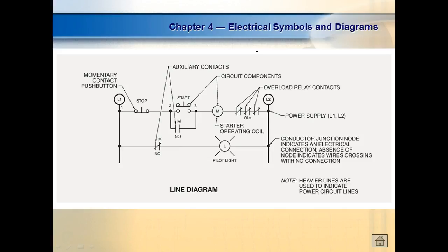Now this is without the transformer, without the power. All our diagrams will start off with the power source. Normally on a ladder diagram, they take for granted the power source is there. But since we have to wire the transformer, they're going to show the transformer. Okay, so this little circle right here, this is our symbol for what? Coil. Relay coil.